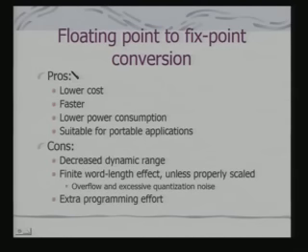The next part is floating point to fixed point conversion. What is a floating point representation? You have a mantissa and you have an exponent. Depending on the value of the exponent, you can have variable precision. When you have a fixed point, that is not there. You have a fixed number of digits allocated for your fractional part.